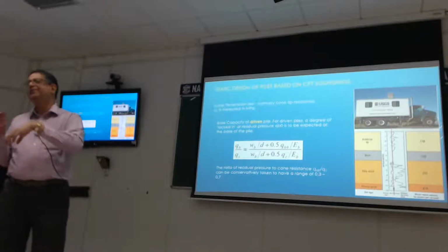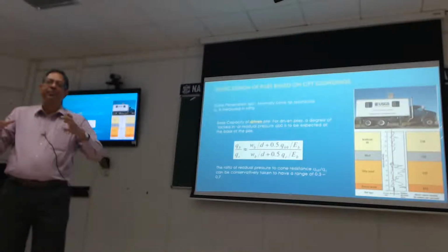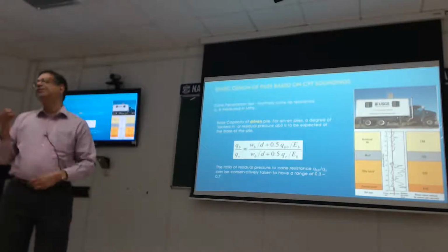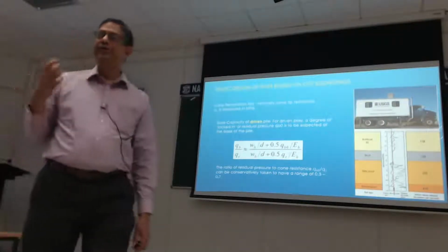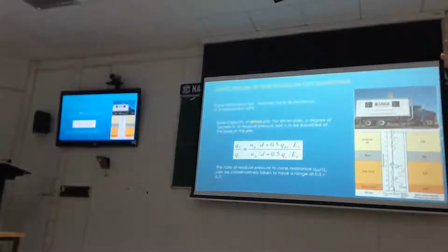The extra density you gain because you're pushing the sand or the soil away from the pile volume is marginal. It will increase your friction angle by a small amount. But what it does quite nicely for you is it creates massive horizontal stresses.